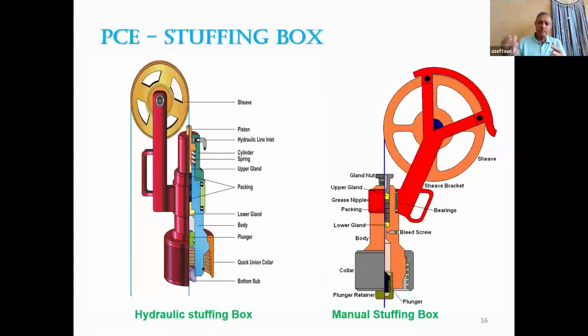What makes the seal in both of them actually is here in this area. What does this area contain? It contains these packings. The wire goes in and out, and this packing is squeezing on the wire, preventing the well pressure from escaping to the surface. And again, I explained that before. If you notice these packings, they are different, maybe in color, in size, in material even. Why are they different in material?